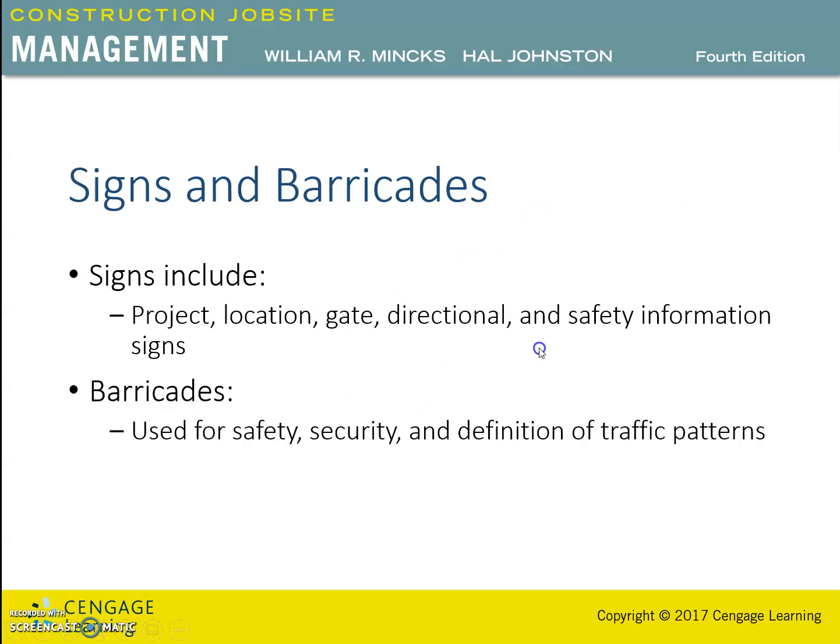The barricades are used for safety, security, and defining of traffic patterns. They are used in the following applications. So, for example, in a safety situation to prevent individuals from proceeding to an area. In dealing with the public, the barricades need to be identifiable and substantial enough to physically prevent passage into the area.